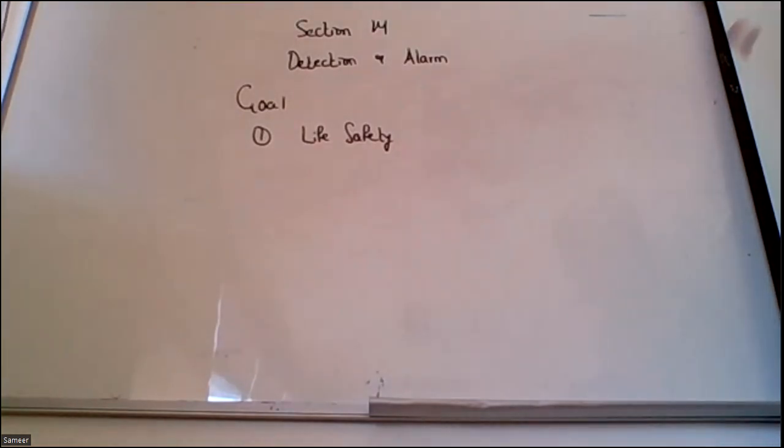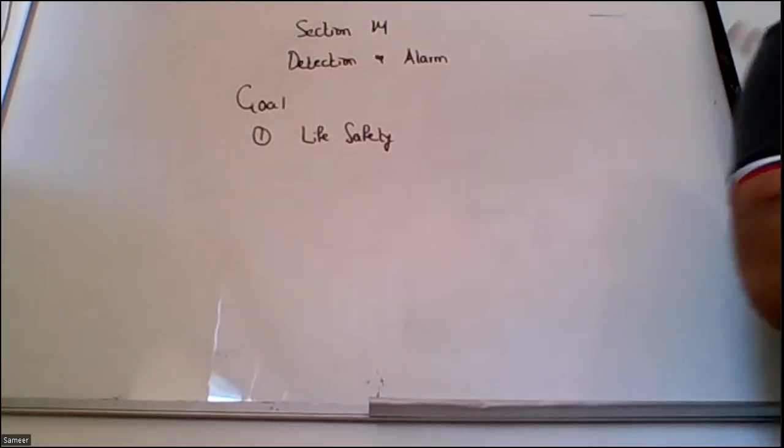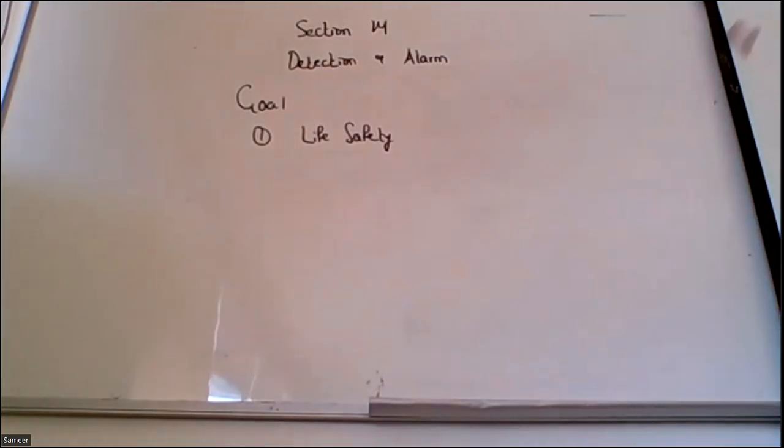If my focus was only the property, I don't require to have sprinklers. I will just have high jet stream water spray nozzles attached, and I can completely flood the whole occupancy. And that's what I do wherever I have explosive industries, weapon industries, explosions, bombs, TNT, black powder, wherever I am storing them. Even if a small spark appears, the complete area is flooded with water. Ultra high speed water spray systems, I do it. Why? Because there the property protection is very important.